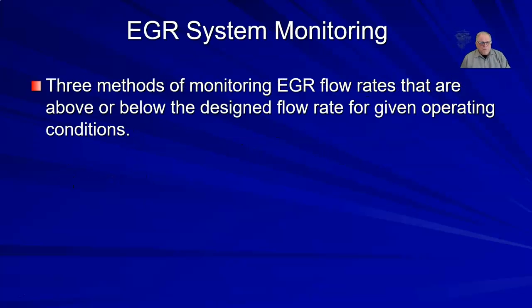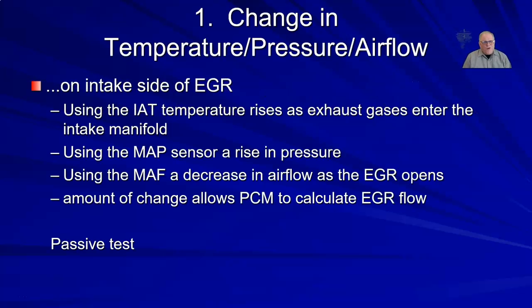Our EGR system monitor is going to be 1 test per drive cycle, or they're going to attempt to test it just once per drive cycle. However, it's not just one quick test. There are several different tests that they may run. We're going to talk about these 3 tests. In our session 1 video, I talked about how they have a passive test, an active test, and an intrusive test. This is where we're going to see those 3 tests occur. I hope you're familiar with the engine operating, because if you're not, this is going to be really hard to follow. So this is test number 1.